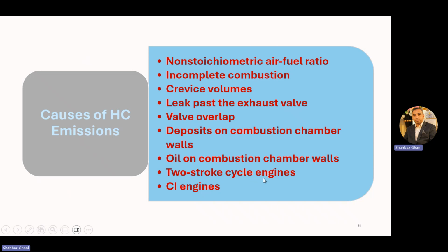Then two-stroke cycle engines, because of their peculiar design, will have some hydrocarbon emission in the exhaust. And CI engines, because they operate in lean regions, have different combustion properties, so there are also some hydrocarbon emissions. So these are a few of the causes for the hydrocarbon emission.